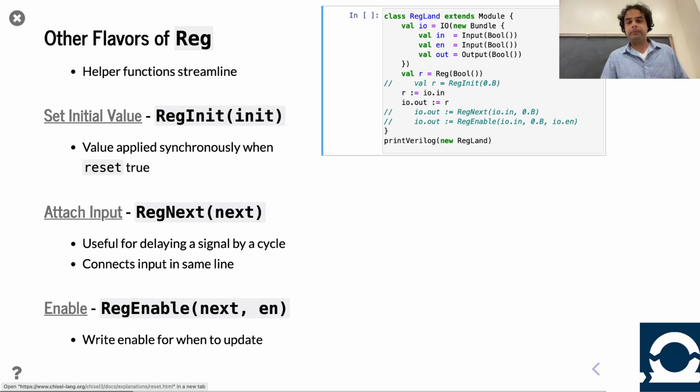And so how does it work? Well, in Chisel, to instantiate a register, you just say Reg, right? Like I said before, when it boils down to Chisel, you are instantiating components and you are connecting components. That's kind of the entire ball game. Everything else is Scala code to get between those statements. But at the end of the day, Chisel is instantiating components and connecting them up. So we instantiate this register called R, and then we connect its input and its output, right?